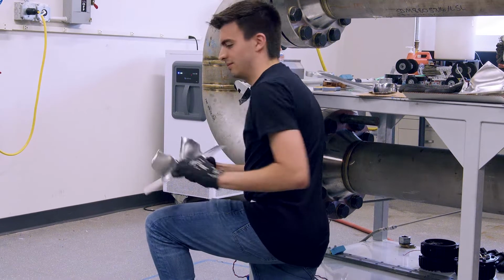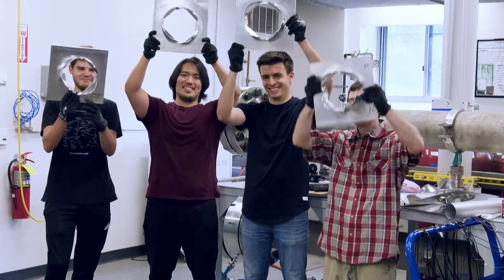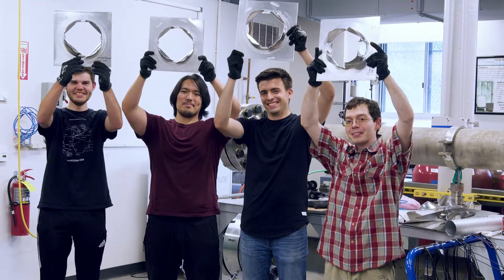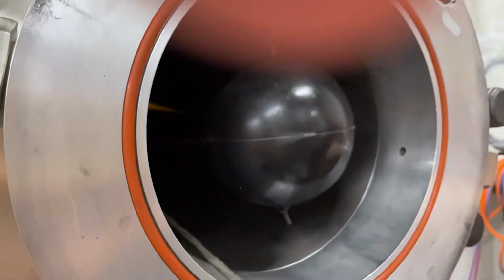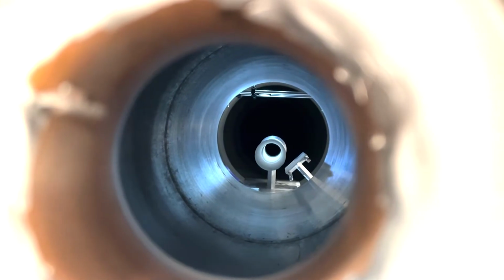When you have the primary diaphragm in here, it has a burst pressure, and that burst pressure is going to induce the incident shock. And that incident shock is like a piston, which basically propels the gas from the driven section through the nozzle as the nozzle expands the flow to Mach 6 at a steady rate over the test article in the test section for about 4 to 6 milliseconds.